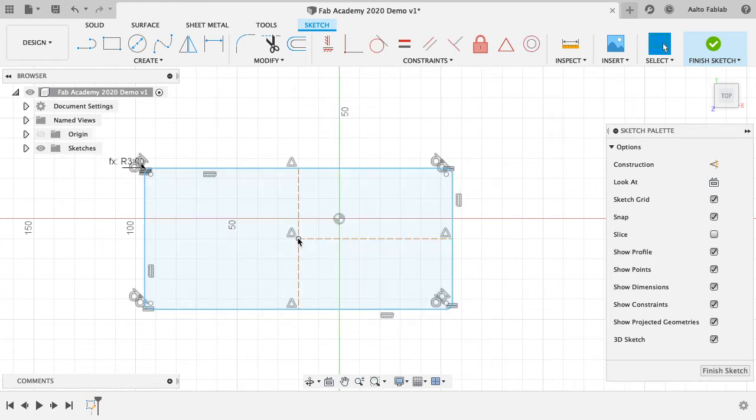And what do we want to do? It created this point also here, and we want to snap this point to the center point of the axis over here. And for this, we are going to use the constraints. From yesterday's lecture, you remember that Neil was talking about the fact that these CAD programs usually have solvers.